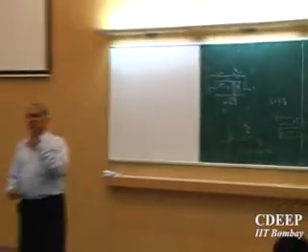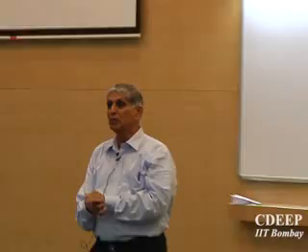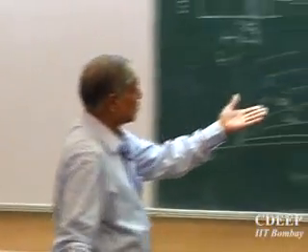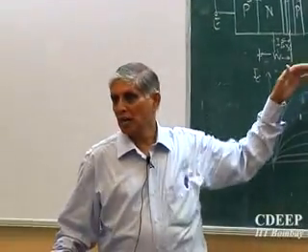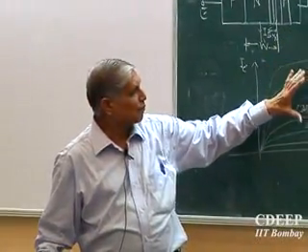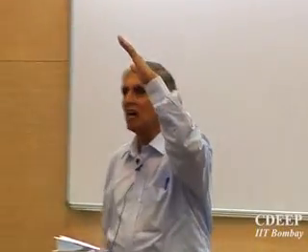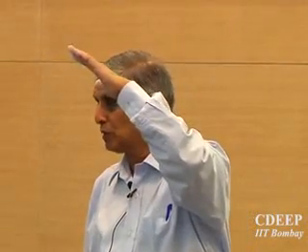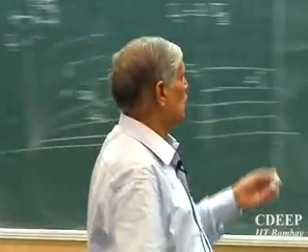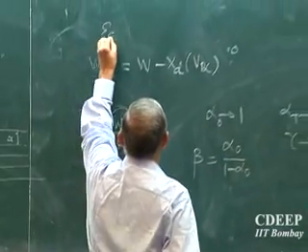So if I increase the reverse bias on the base-collector junction, beta actually increases. And this characteristic is telling me that if I move to higher VBC, these gaps are increasing compared to these gaps. Therefore there is a finite slope in the IC-VC characteristics, which shows that beta is changing with different VBC values. Is that correct? This effect is called the Early effect.